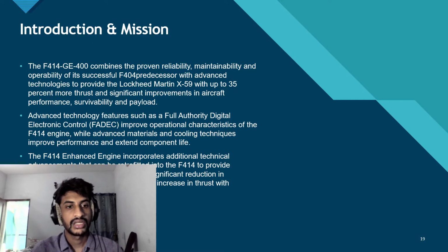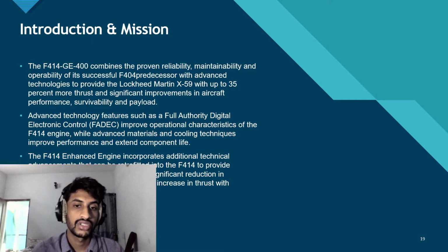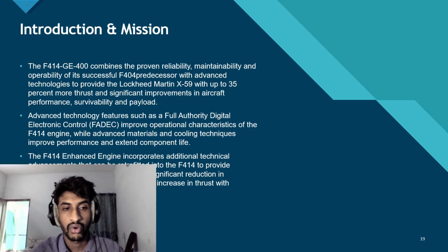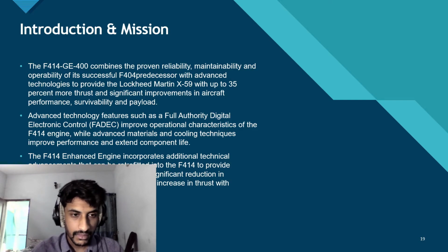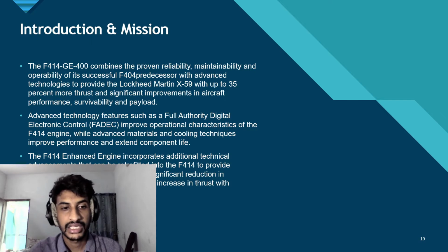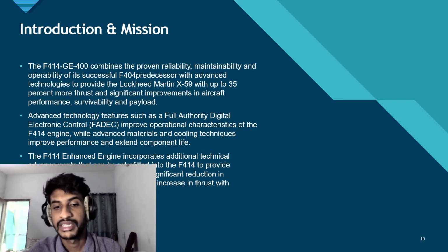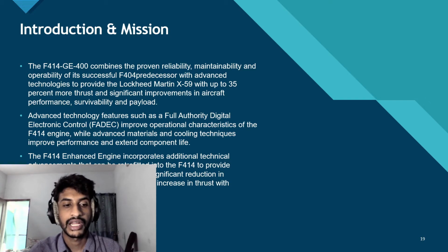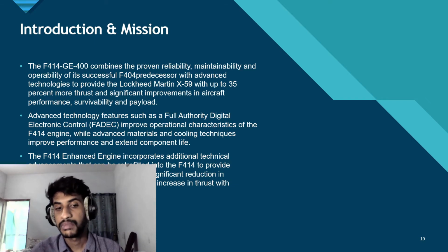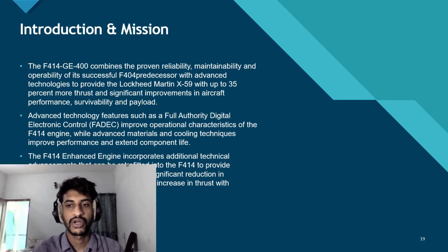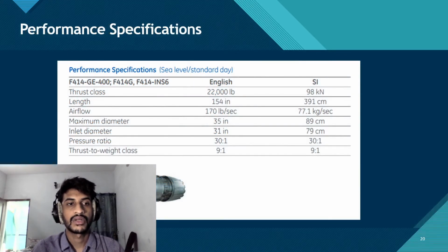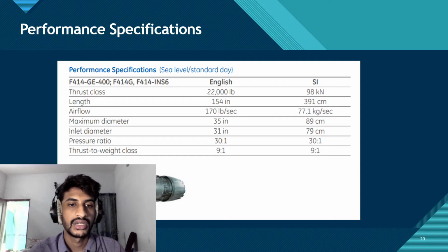and payload. The advanced technology features include full authority digital electronic control. This improves operational characteristics of the F414 engine, while advanced materials and cooling techniques improve performance and extend component life. The F414 enhanced engine incorporates additional technical advancements that can be retrofitted into the F414 to provide improved component capability for a significant reduction in ownership cost or up to 20% increase in thrust with improved specific fuel consumption. Now the specifications of the F414 are given over here.